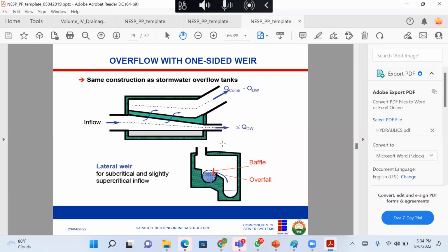So basically, this is what we call a stormwater overflow. Now, this is like a surface. When the water level here rises, what happens? The top clear water, the decanted water, will overflow. When it overflows here, it goes to a combined sewer overflow. It's more like a tank. In the developed world, they build a big tank so that excess water will flow into that tank, water that is not too diluted. Then immediately after the rainfall ends, they will discharge it into the treatment plant using the other bypass.